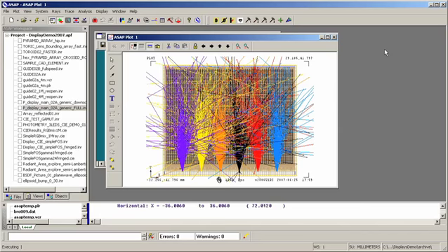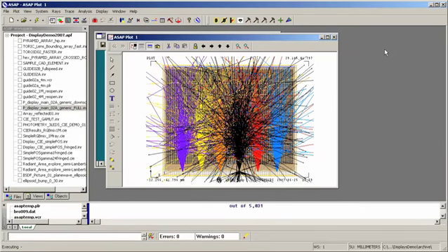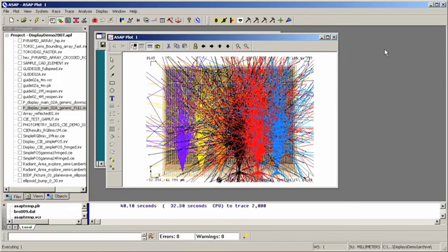But the grooves on top, the little rib structures on top, actually help to cross the rays laterally so that the LEDs fill in the gaps between themselves. And the first rays we see are rays that are simply totally internally reflected, but we also have a scattering process on the foil sheet on the bottom.